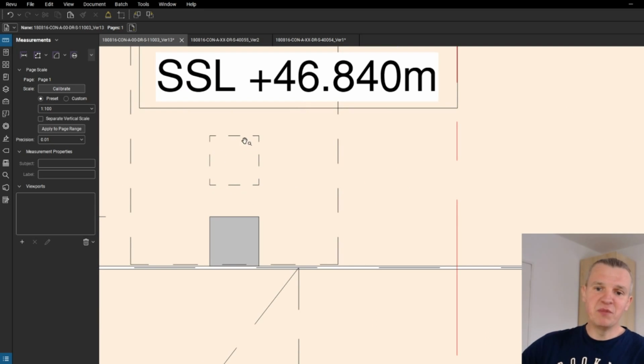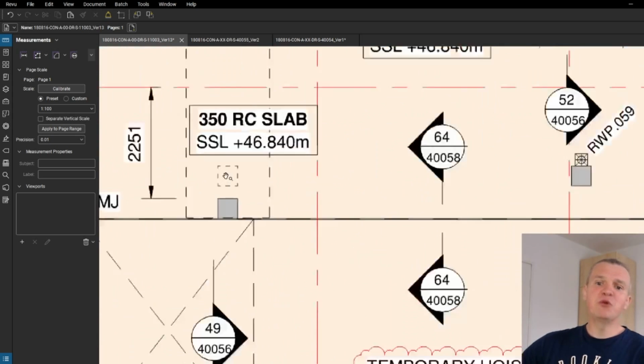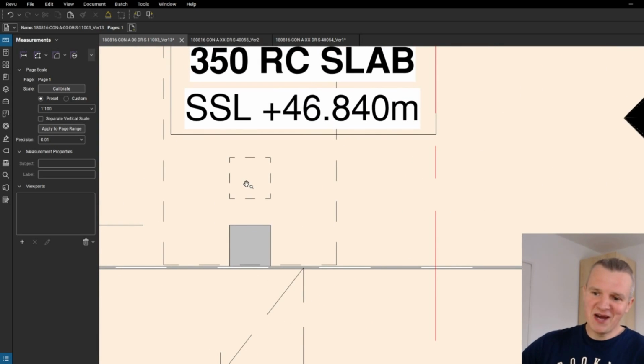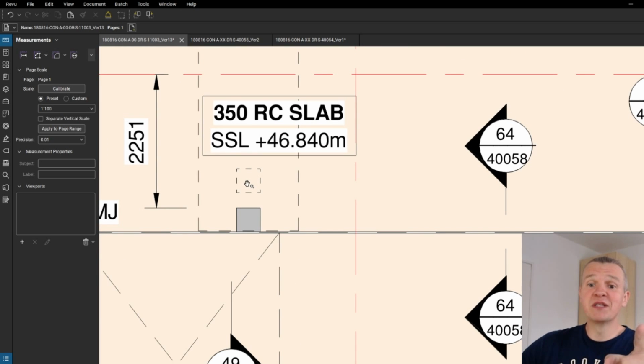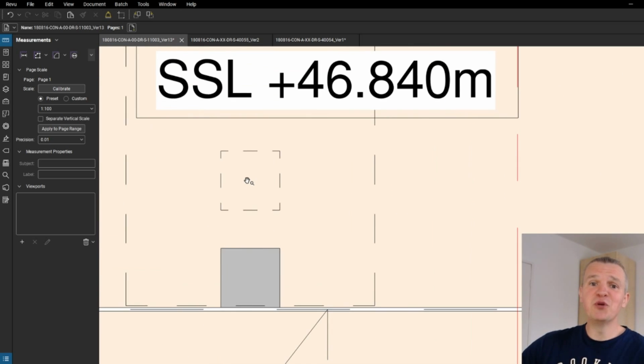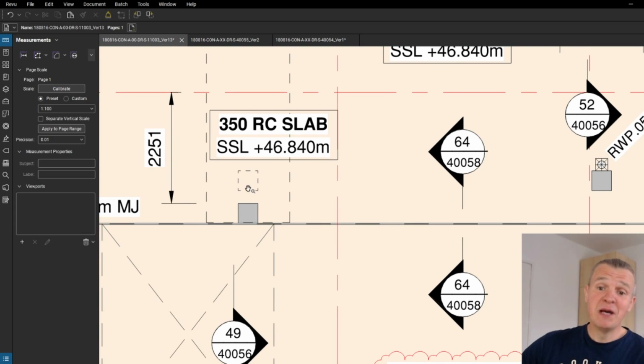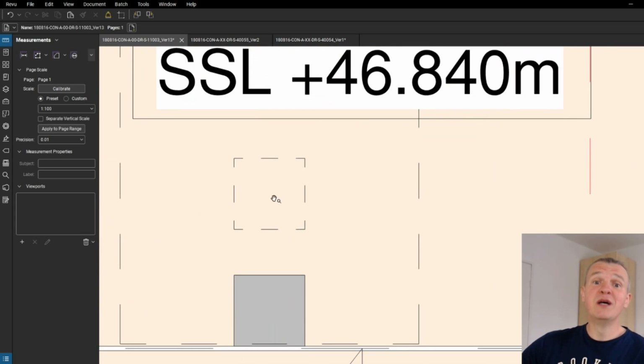So under the beam there will be a column, and obviously, guys, once you're going to be doing this column, and this is maybe more advanced and not so much with the drawings really, but that's the information taken from the drawings. Once you're going to be pouring this column, you need to remember that there is a beam on top. So this column should be poured to the soffit of the beam, not to the soffit of the slabs.